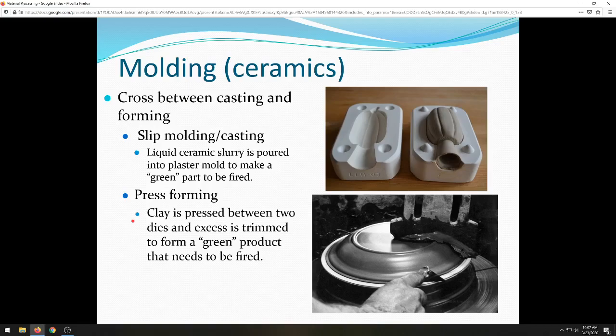You take a clay. It's not a liquid. There's no special tricks to it. In this case, it looks like they're making a shallow bowl or a dinner plate. So this piece is spinning here. You put the clay onto the mold, onto a form underneath here that's the inside of the plate or bowl. You press it down there, and then you push this arm.